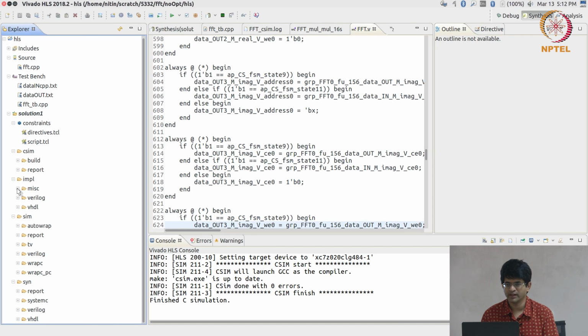What they do provide, on the other hand, which is much simpler to implement, is functional equivalence checking. What that means is you already have a test bench, so why not run that same test bench against the generated Verilog code and see whether the same results come out. As you can imagine, that is not bulletproof.